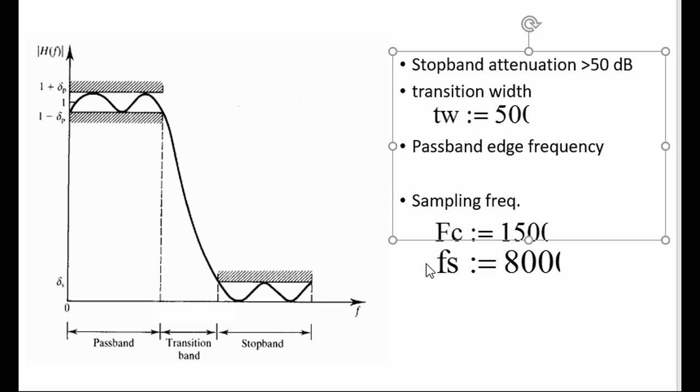Alright, so let's talk about filter design. Remember the Bode plot, so this is a frequency spec. So we can see this is a typical low pass filter. We want all these frequencies to go through and those frequencies not. So there's just a few definitions. This is the pass band, so it means these frequencies must go through. Transition band, so it's from the part that you want to go through to the part that you don't want to go through. You can see the amplitude is going down, so some of these frequencies might still slip through if you don't want them. And then the stop band, that's the part that you don't want to let through.